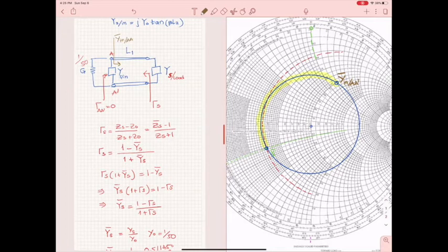To be accurate with the use of the words, it is called susceptance. But in any case, we add the stub to be able to cancel the reactive part of the normalized admittance. The stub can only impact the reactive part of an admittance.